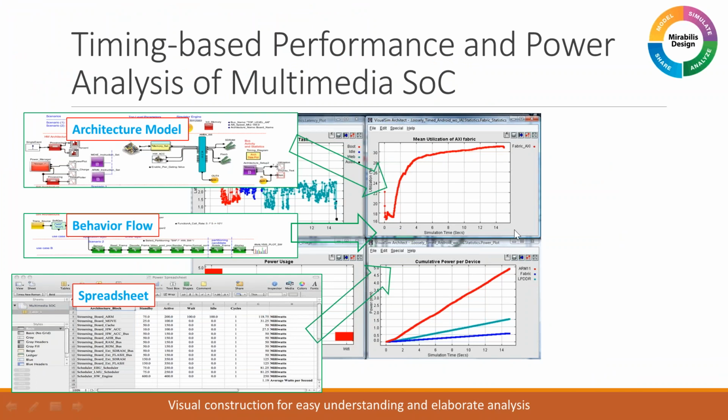So looking back at that model that we constructed, as I'd mentioned, we had 3 parts to the model. The first part was the architecture, which is your hardware and software platform. Remember, I just showed you only the hardware: the processors, the buses, the memories, the caches, but you can also incorporate runtime environments, schedulers, operating systems, things like that as well.